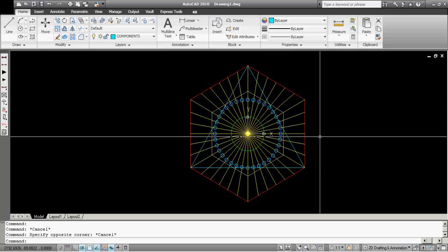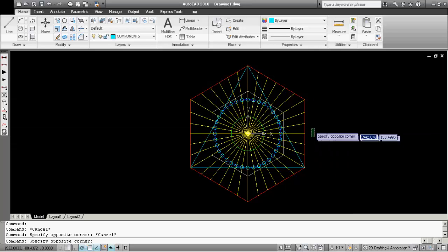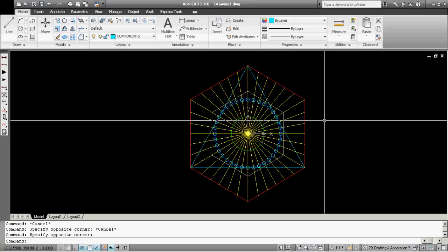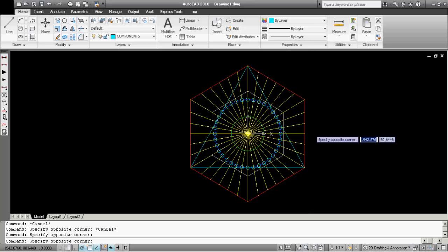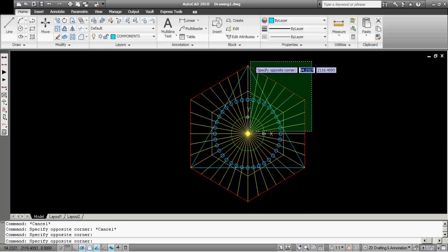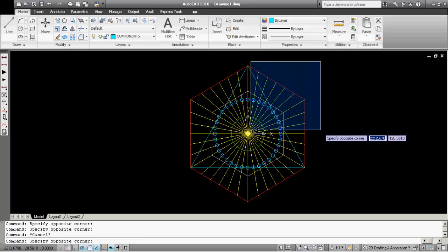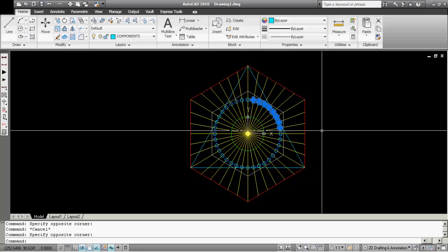having different effects. Right to left selection, displayed with a green shade inside the selection window, will select everything included plus everything intersected by the selection window. Left to right selection, displayed with a blue shade, will select just things inside the selection window.